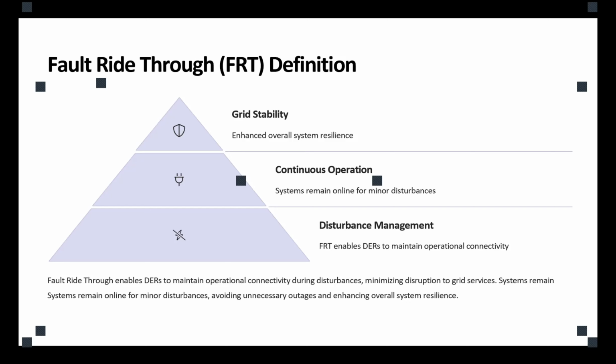So that means when we talk about the transient, it's not just detecting whether faults happen or not, or what kind of incident happened. We also have to recognize whether we can tolerate through that incident or we have to clear it out. So now we have two conditions. The second condition, we call it fault ride-through.